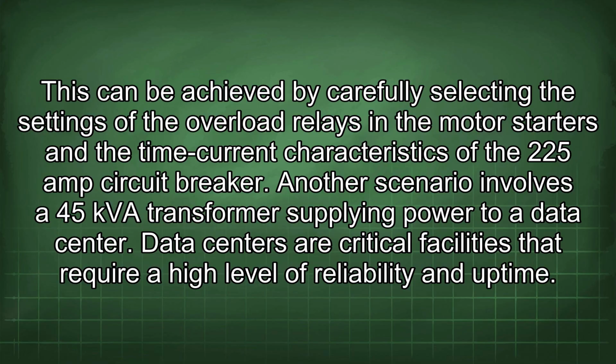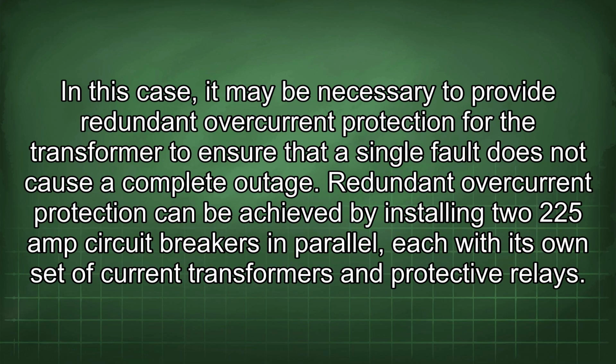Another scenario involves a 45 kVA transformer supplying power to a data center. Data centers are critical facilities that require a high level of reliability and uptime. In this case, it may be necessary to provide redundant overcurrent protection for the transformer to ensure that a single fault does not cause a complete outage.